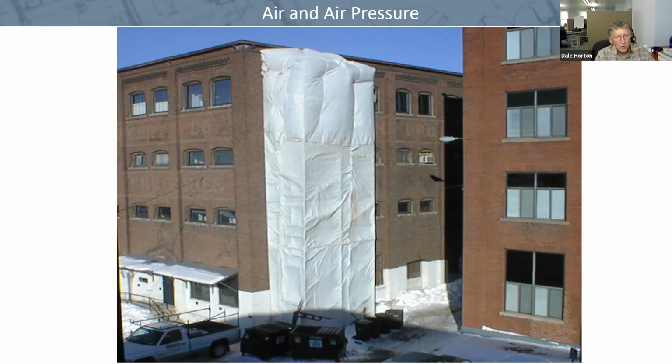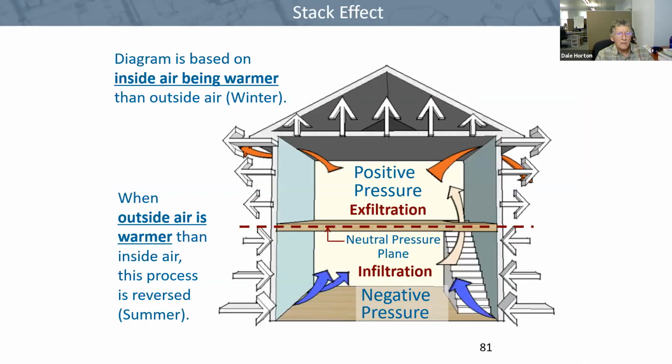Why does a plan reviewer or a designer or a builder care about this? Well, nowadays, when we're doing building tightening, testing with blower doors, we're testing ducts, and we're considering the pressure differentials within buildings. All of a sudden, folks that are involved with the building industry are being confronted with issues that have to do with air pressure. Stack effect is a term used for the pressure that's created higher in the building due to the positive pressure of less dense warm air rising, more dense cooler air following, which creates exfiltration higher in the walls and infiltration lower in the walls.